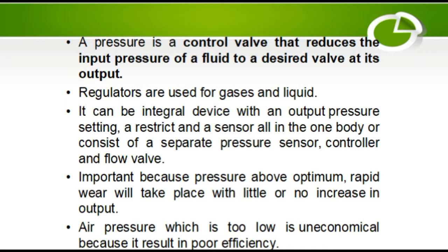It can be an integral device with an output pressure setting, a restrictor and a sensor all in the one body, or consist of a separated pressure sensor, controller and flow valve. Important because with pressure above optimum, rapid wear will take place with little or no increase in output. A pressure which is too low is uneconomical because it results in poor efficiency.